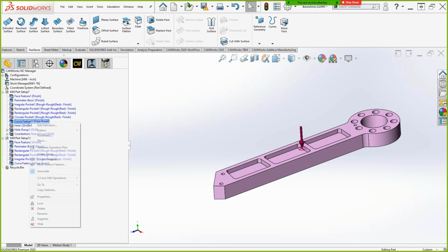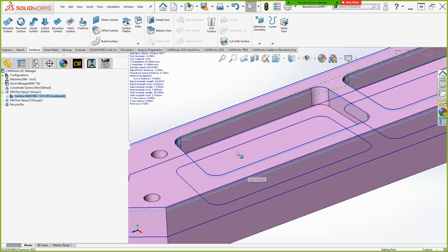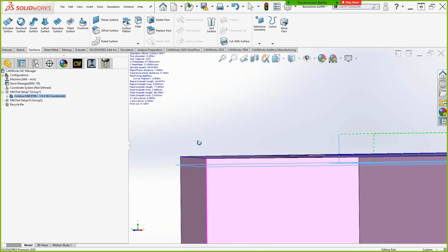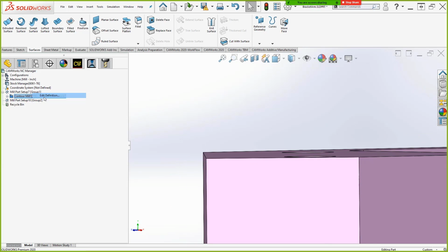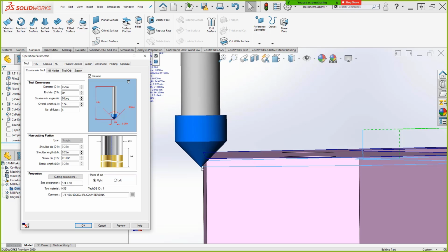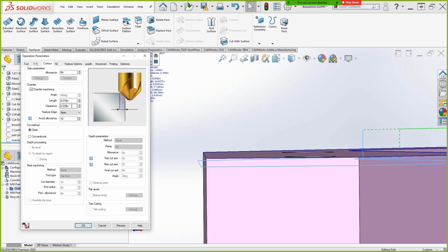Let's right-click on the curve feature here and just use that edge break strategy. Obviously, it comes out with a contour mill using a countersunk tool. Generate toolpath. Exactly what we expect to see, right? You can understand how the 45-degree tool works if we just show it. Why not? If that 45-degree tool was placed bottom dead center on that toolpath, we see that nice edge break going all the way around. And it's real easy to jump in and modify some of these different values for sizes and clearances and things like that.